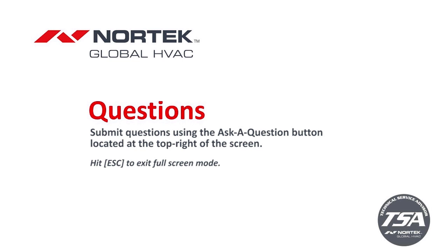Another question that came in is, can you use the charge application app for a restriction type scenario? Not necessarily, because when you have a restriction scenario, your pressures and maybe your line temperatures will reflect that kind of troubleshooting aspect. So it's not really for if you've got a plugged filter dryer, for example, or maybe you got a piston or a screen that's got some debris in it.